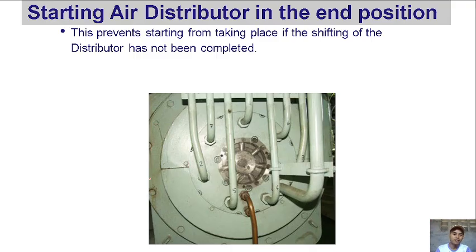Okay, next we have the starting air distributor in the end position. So this prevents starting from taking place if the shifting of the distributor has not been completed. So pag nasa alanganing position yung distributor, hindi siya magsa-start.